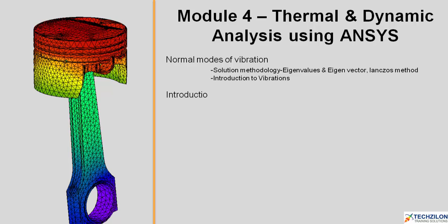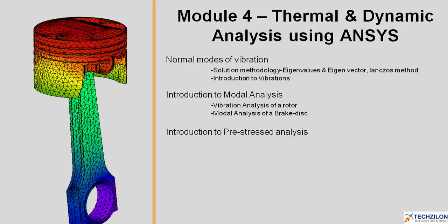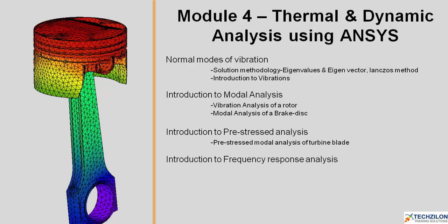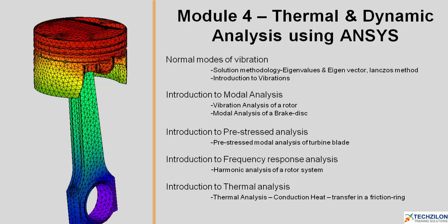You will then be introduced to modal analysis, where you will learn vibration analysis of a rotor, modal analysis of a disc brake. You will then move on to introduction to pre-stressed analysis. We will run a pre-stressed modal analysis of a turbine blade. You will later be introduced to frequency response analysis, under which you will learn harmonic analysis of a rotor system. Finally, you will have introduction to thermal analysis, under which you will have thermal analysis, conduction, heat, and transfer in a friction ring.